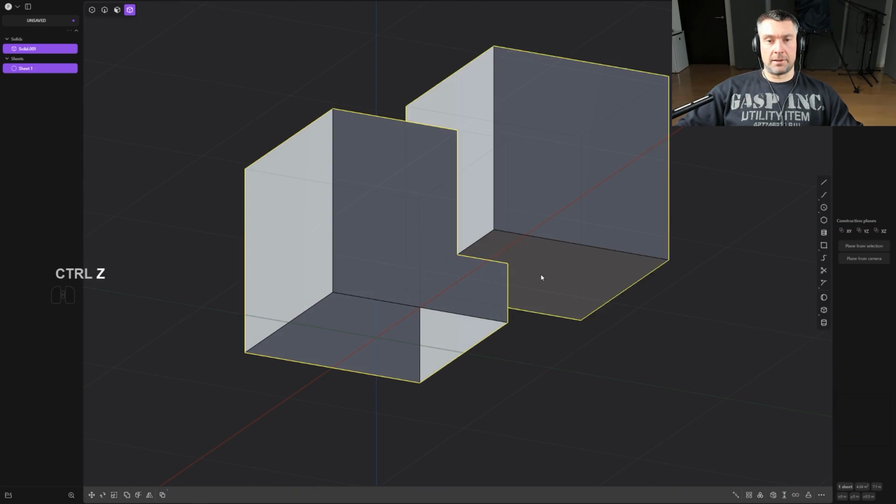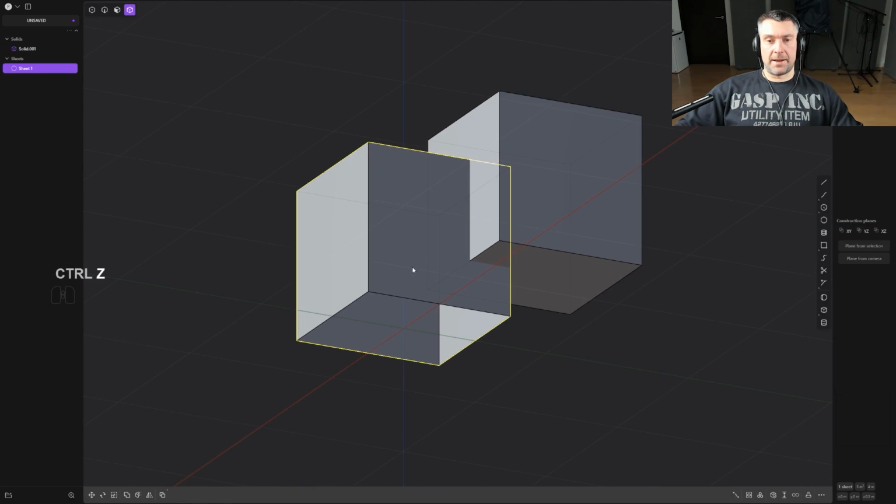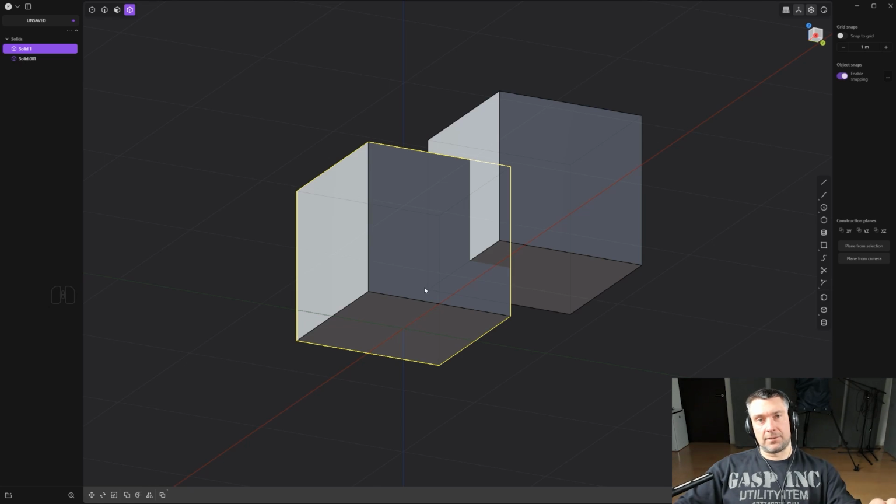And the way you do that, basically, is by patching it. So select the mesh and you can patch it, and it's going to patch all the holes that it can patch. Unless the hole isn't patchable, you need to kind of manually close it, because it's too difficult for the patch command to be executed.